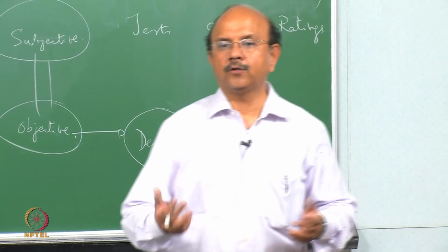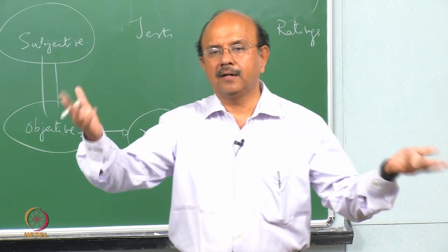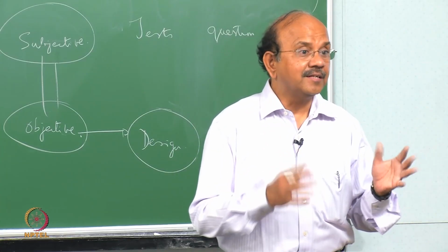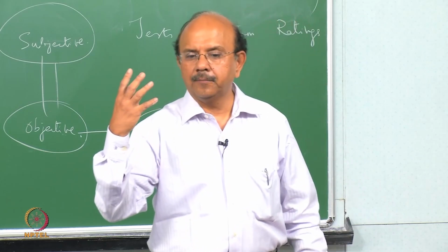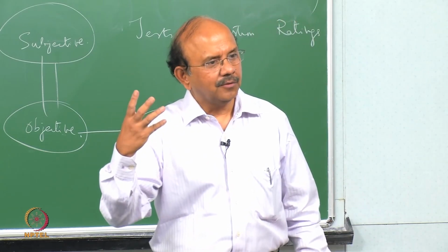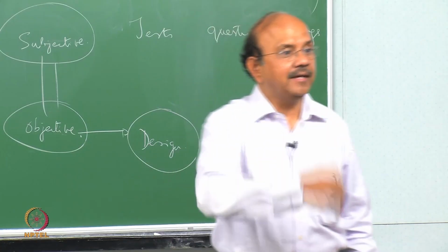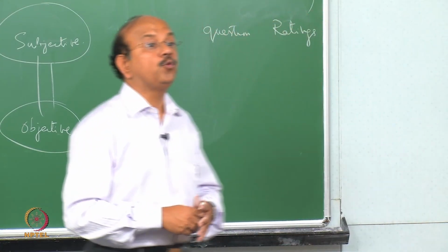If it is less than the yield, say yield divided by a factor of safety, or permissible stress, then it's fine. So there you calculated it and you had a fantastic criteria function which told you to compare these two, and if they're less, fine. Here I do not have a criteria function because I have too many parameters.